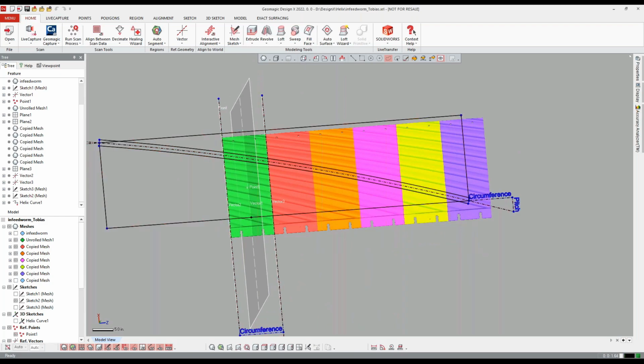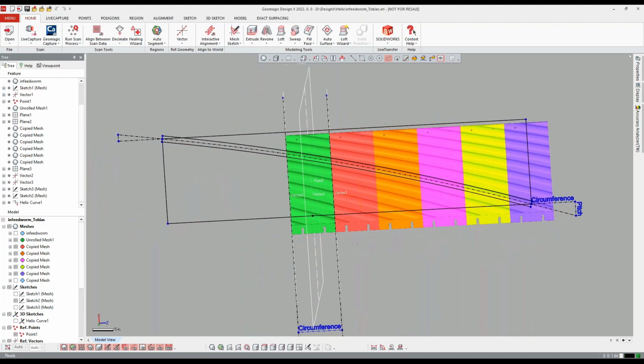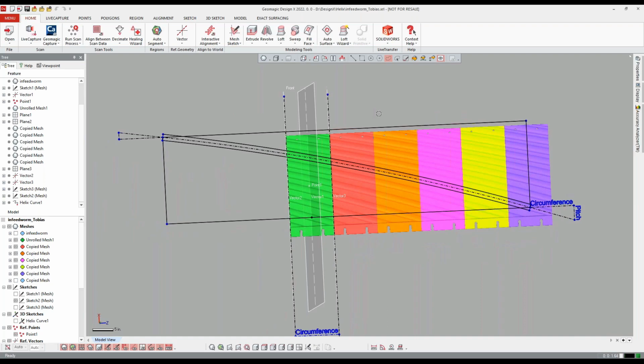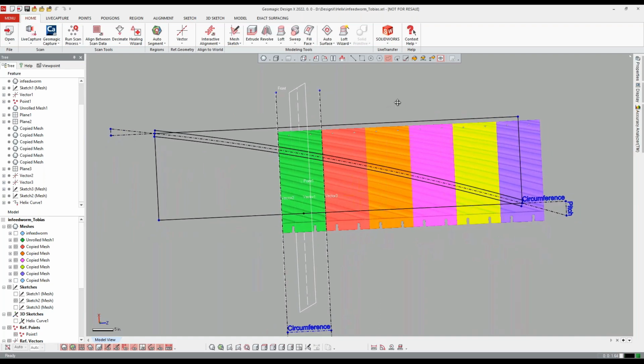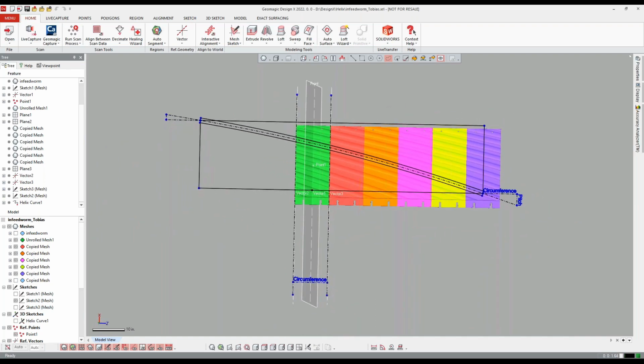And then what we can do is stuff like this. This is what we use for circular cams and shift drums and all kinds of fun stuff like this. But at this point, as this is a radius, if this was a straight line, you'd know it's a linear, non-variable helix. So it's just a straight screw. So as this turns into an arc, you get a radius. If it was a couple of weird radiuses or a spline, then there could be some function to it as it's conveying.